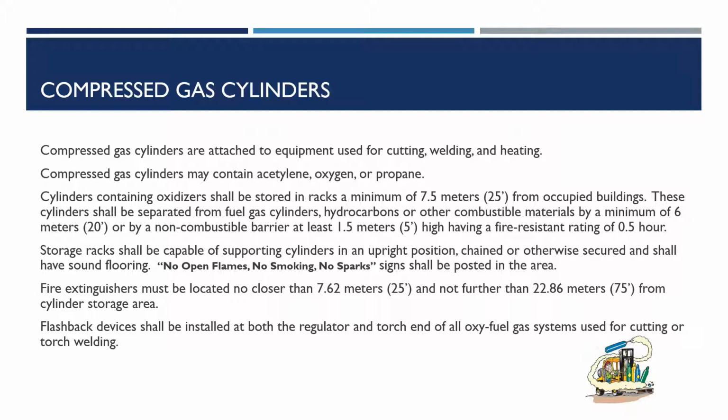Storage racks shall be capable of supporting cylinders in an upright position, chained or otherwise secured, and shall have sound flooring. No open flames, no smoking, no sparks. Signs shall be posted in the area. Fire extinguishers must be located no closer than 7.62 meters or 25 feet and not further than 22.86 meters or 75 feet from the cylinder storage area. Flashback devices shall be installed at both the regulator and torch end of all oxy-fuel gas systems used for cutting or torch welding.